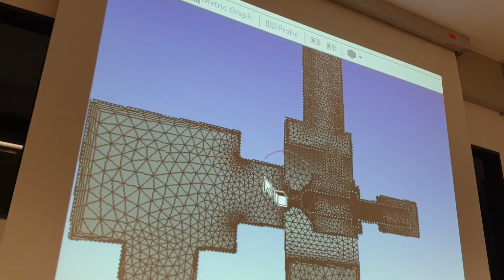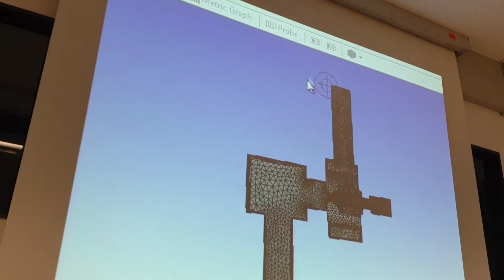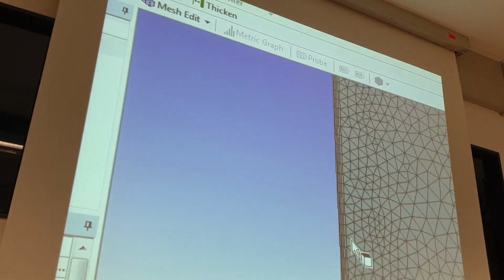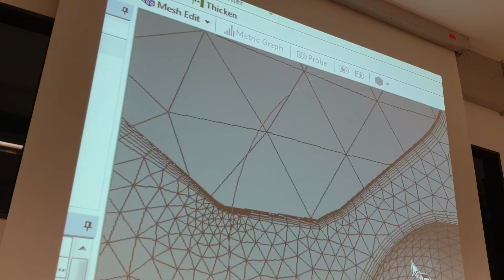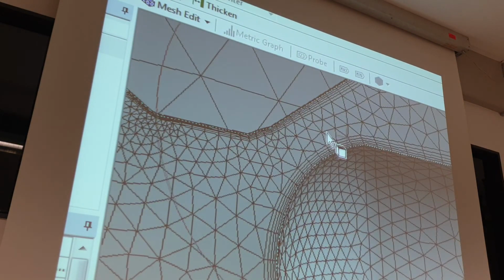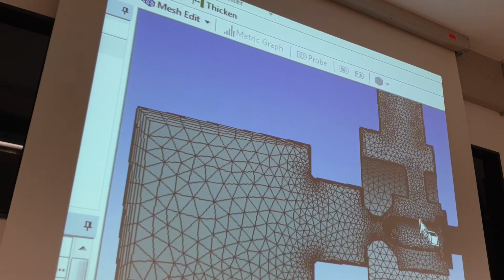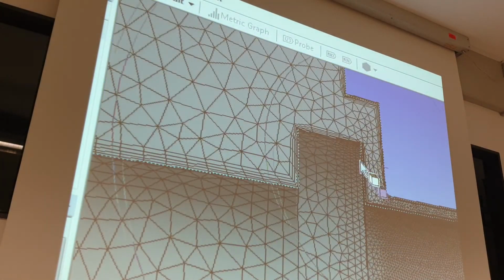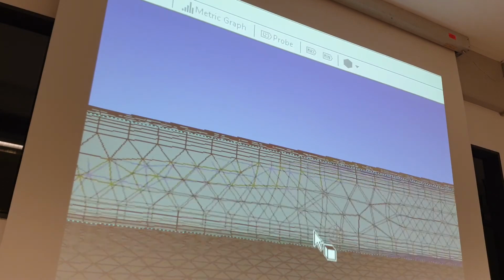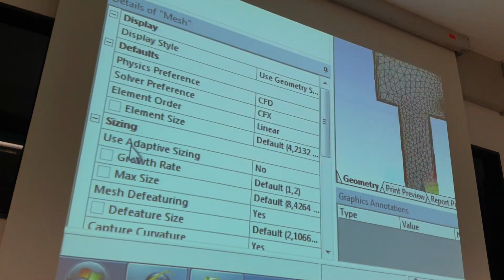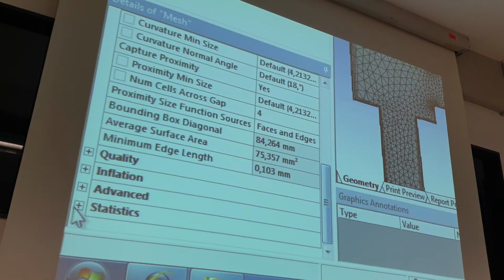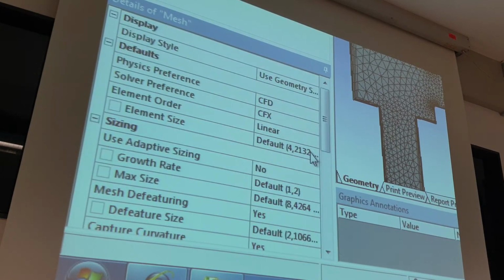Okay, now I create this proximity for elements. Okay, it looks too fine, maybe, yes. It looks too fine, but it looks good here, yes. We see we have this inflation, 5 elements near the wall, really small, to calculate these flow gradients. And here we have also, yes, really fine. Okay, maybe we have too fine a meshing. Maybe it was not so good a solution, 200,000.